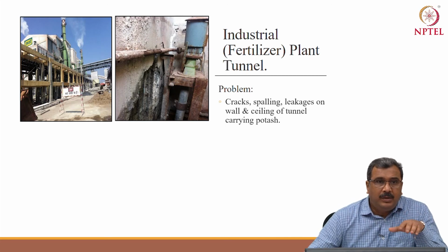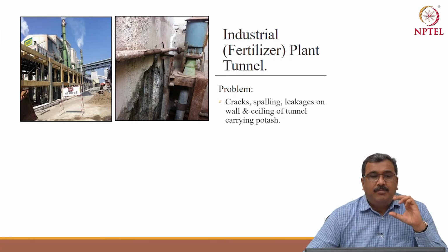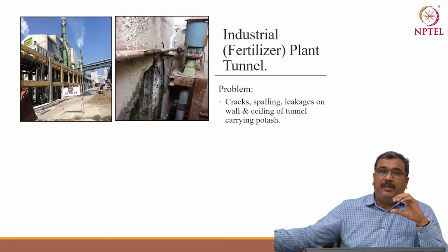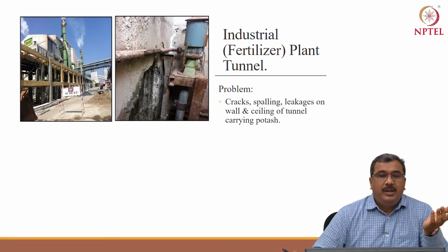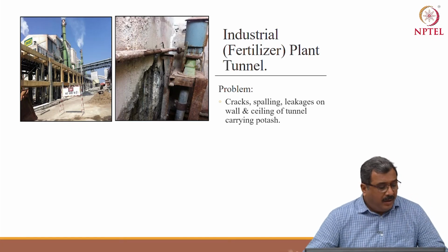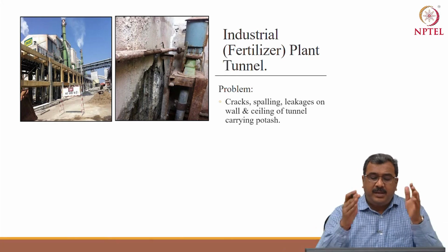Below the ground level, 5 meter is the height of the tunnel. So at the starting it is minus 5 meter below the ground level and it slopes towards minus 11 meter. And the sea water, groundwater level is minus 2 meter. The tunnel wall thickness is 1 meter at the bottom and 600 mm at the top.